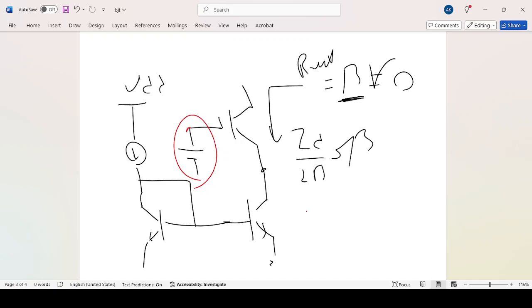But the amazing thing here is you didn't do that by using this configuration, because VBE is still not defined by this guy, and this node could be flexible to define VBE in a way that wouldn't be affected by the effect of IS and other stuff in the circuit.